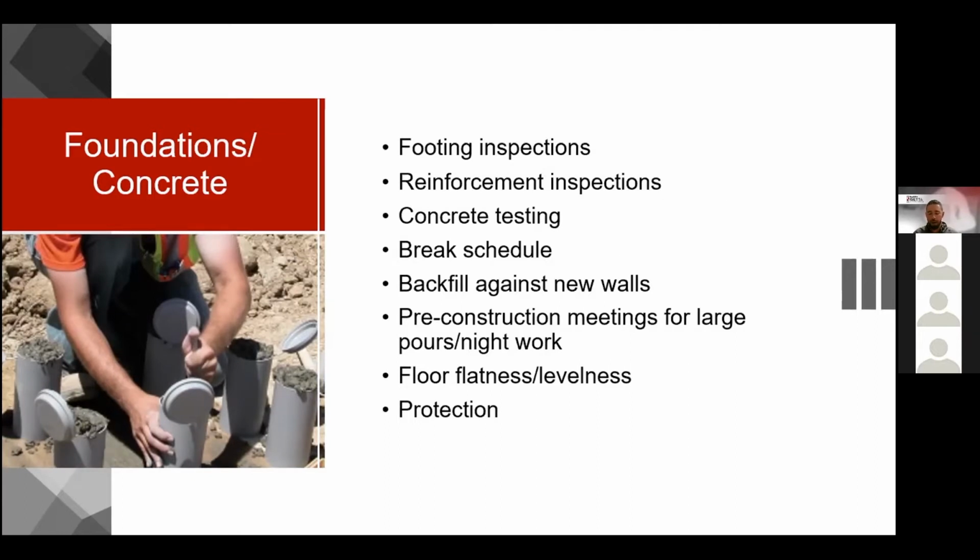And then there's also break schedules. It's a great thing that we discuss. Our other Eric will be taking care of discussing the break schedules with you. But it could be 7 days, 28 days, holds, and that all gets determined at the pre-con meeting. Sometimes they may need a rush and we need a 3-day because we want to run lifts on a slab for MEP, or we want to remove shoring to get backfill in.